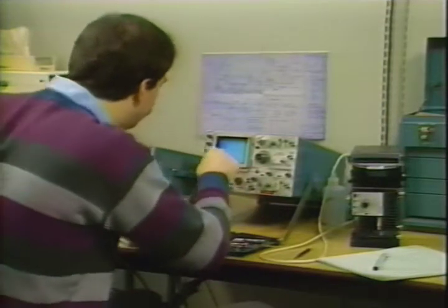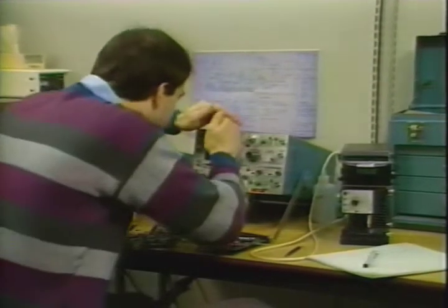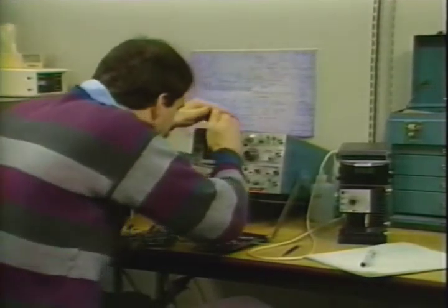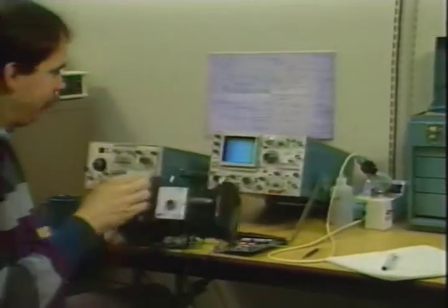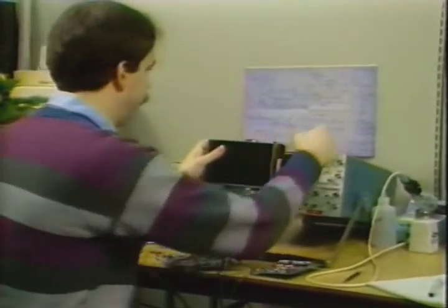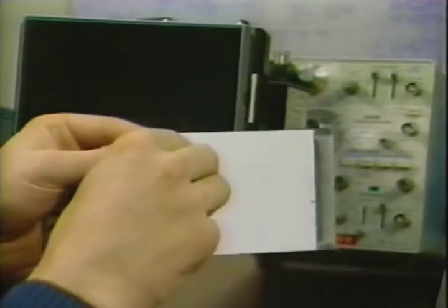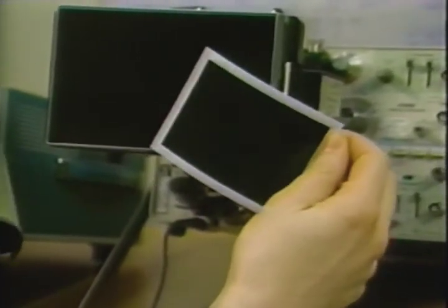Sometimes, with a great deal of effort, we can record an event on a normal scope, if you know it is there. We can use a high writing speed scope with P11 phosphor, a fast camera, high sensitivity film, and perhaps pre-fogging techniques to achieve the very highest writing speed, if we know the event is there. But sometimes, our best efforts fail.